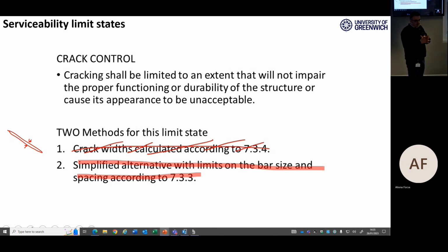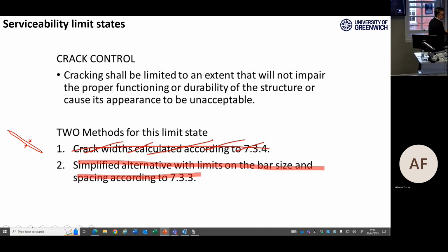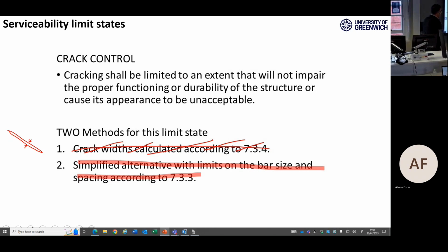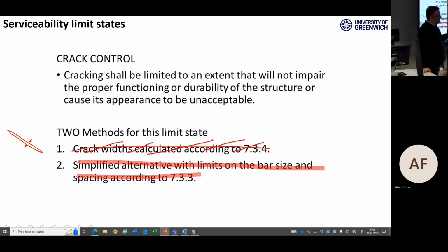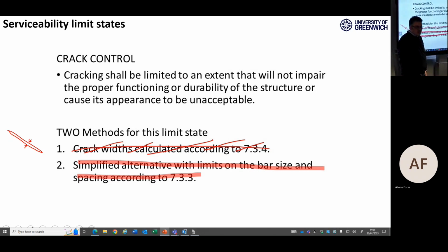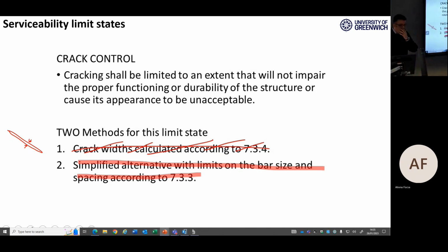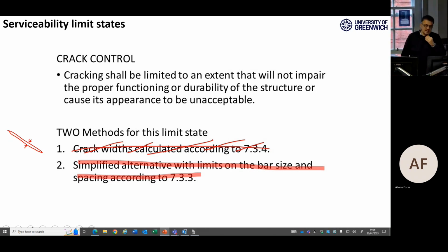It's very small, but it happens. So with this opening and closing, you will grab some carbon inside, and it's very hazardous for your rebars inside your bridge main tower, main beams, or any sort of reinforcement you have inside the concrete section, right? So we need to ensure that the cracks are reasonable.